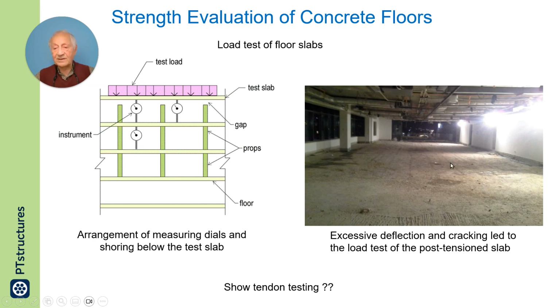When you want to load test this or any floor like I am showing at the top, you shore the floor that is going to be loaded in case it collapses, because the load you put is the ultimate factored load. It's not reduced load. It is the maximum load for which, under unusual circumstances, the floor is designed. This floor has to pass the factored load applied on it before it could be declared safe.